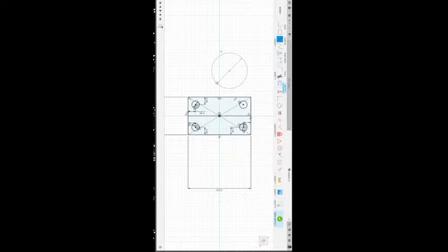Then obviously the dia will be 8. I'm just pressing 8, enter. So I want this here. What I'm going to do is coincide constraint. Coincide constraint automatically brings this circle to this line. Boom. Let's see the magic.